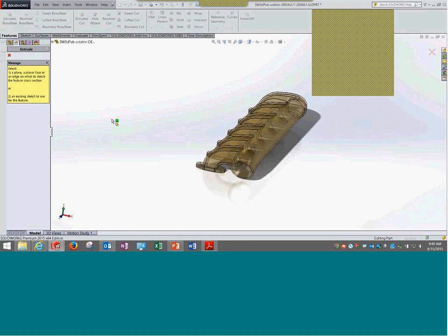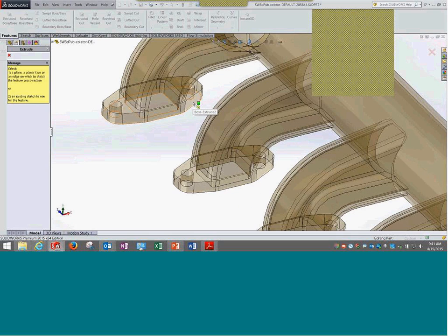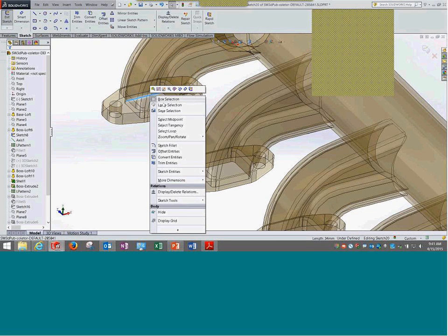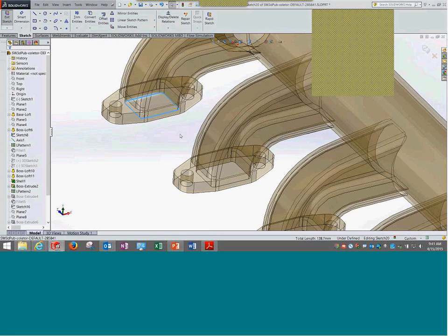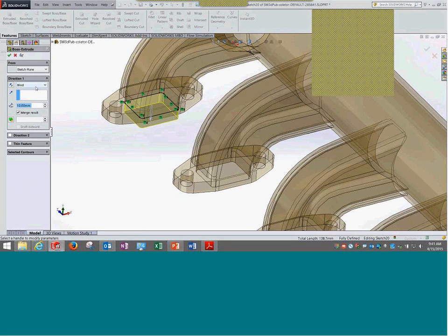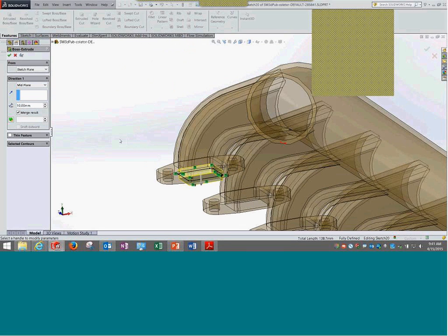So just try to fit your thinking towards this feature. I create a view, select a plane, and thereon I need to use the convert option to select the appropriate geometries. So I am required to set this, convert it, then select the feature, then select extrude, and I'm going to select mid plane. That's it. So these six steps are reduced by using that ready-made option of create lids.